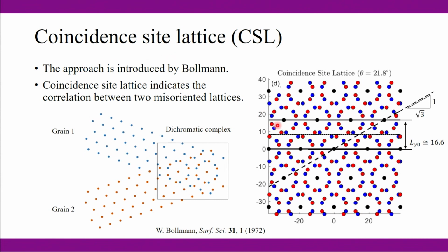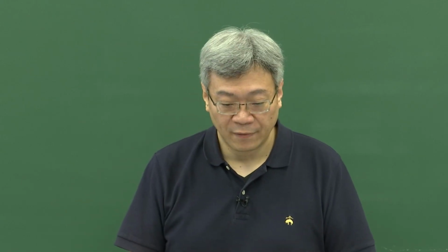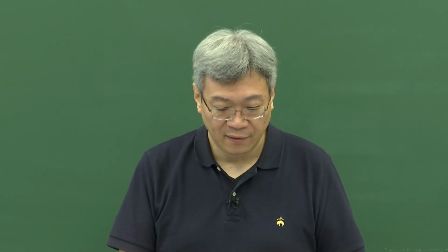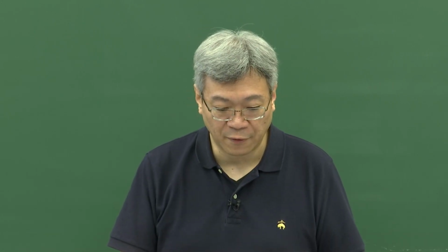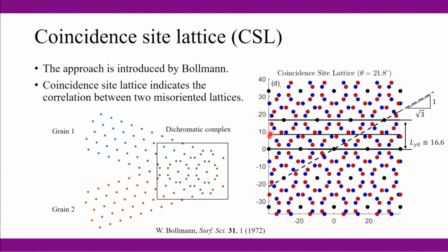All right. So for example, if we properly set up our bicrystal, the grain boundary actually is this line across the coincident lattice sites, because that will make the top and lower grain very symmetric. But if the stress is large, the grain boundary can move to somewhere higher or lower. But as you can imagine, the grain boundary structure is going to be different.